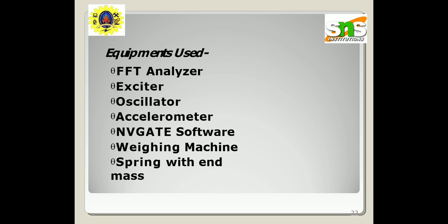The natural frequency of the tuned mass damper is basically defined by its spring constant and the damping ratio determined by the dashpot. The tuned parameter of the tuned mass damper enables the auxiliary mass to oscillate with a phase shift with respect to the motion of the structure. In a typical configuration, an auxiliary mass hung below the nacelle of a wind turbine is supported by dampers or friction plates. So, dampers in buildings and related structures are huge concrete blocks or steel bodies mounted in skyscrapers or other structures.